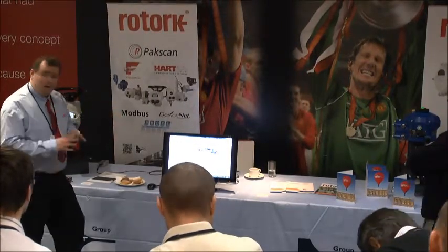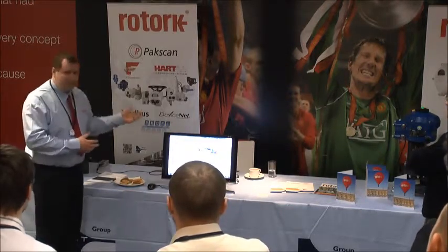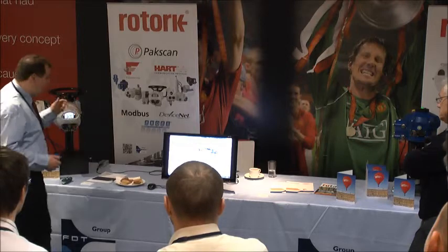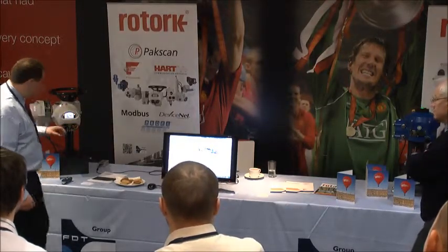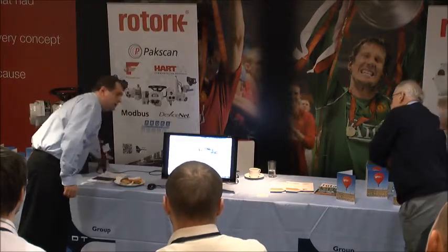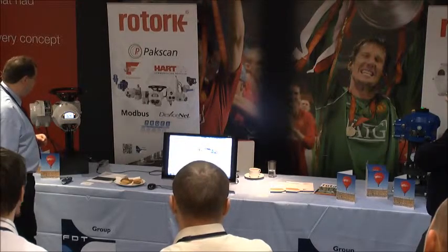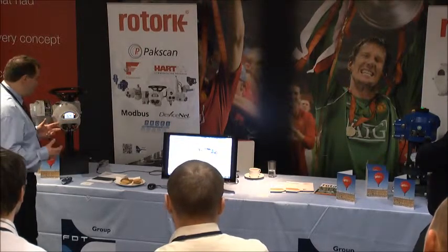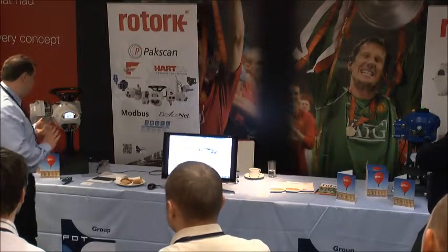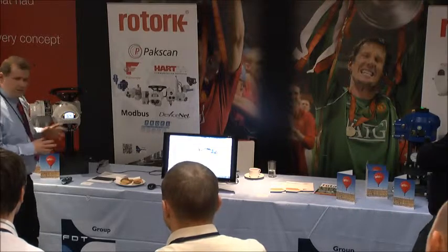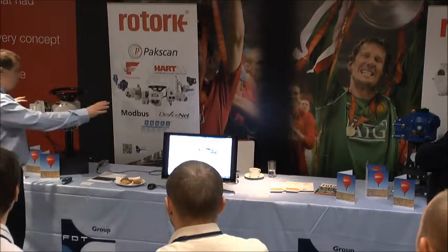Now it could be running as part of a DCS PLC system. You can also run it just on a laptop or a PC. What I've got here is an interface to give a Profibus connection, and I'm using this Brad communications device. So again, not Rotork, it's another interoperability thing. We're just using a third-party device, and that gives the Profibus interface functionality to the laptop computer. There are ones from Softing and others too, so now that I've got a Profibus connection, I have two actuators here.